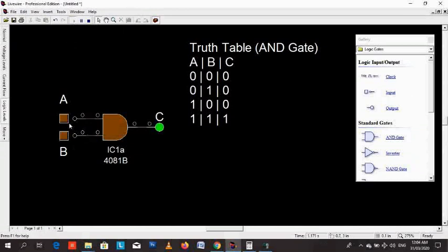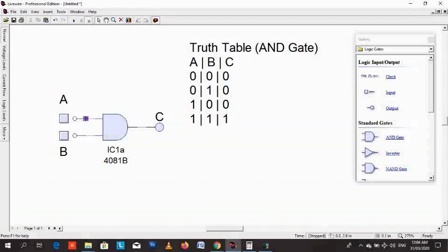So, like I said, with toggle, you click, you can change it. You can change the inputs from 0 to 1 just by clicking on it, then run the simulation. So basically, we spent most of today's lecture in the logic levels window. This is normal output on the normal window.